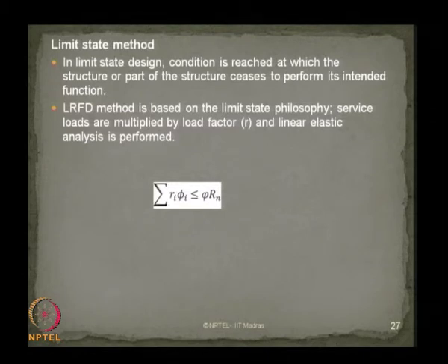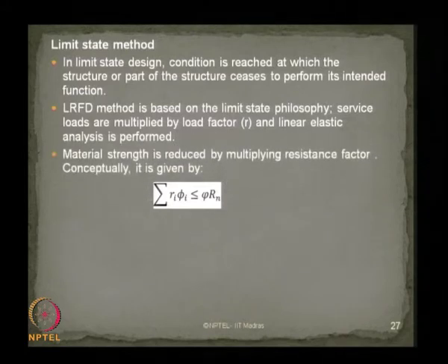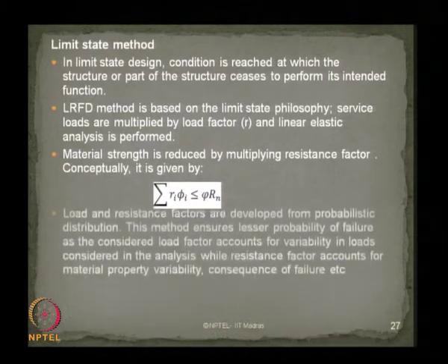Service loads are generally multiplied by a load factor, and the linear elastic analysis is performed to compute the values. The material strength is of course reduced by multiplying by a resistance factor. Conceptually, it is given by the following equation, as you see on the slide now.